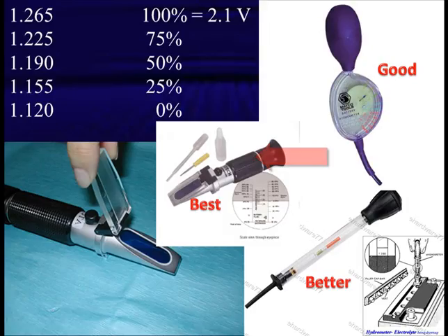We look up and we find one of our cells in a fully charged battery is down around 1190, 1200 specific gravity. That cell is never going to charge up with the other cells in series with it. All the current in that cell to bring the specific gravity back up has to pass through the fully charged cells. If you have a weak cell that's not fully charged, as indicated by specific gravity, no amount of charging is going to bring it back because in order to be charged, the current has to flow in series, like we showed with that little 9-volt battery.